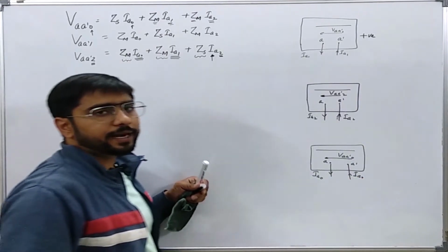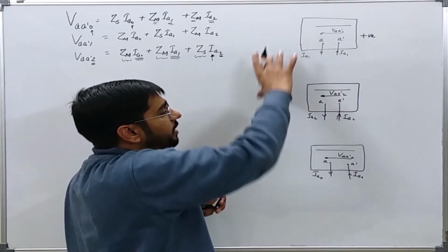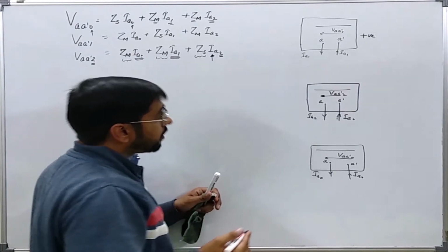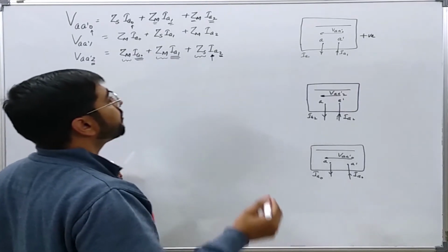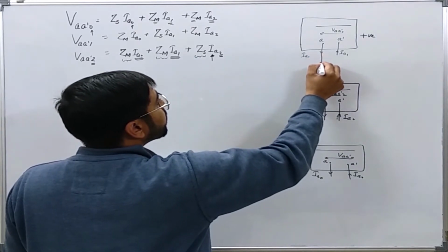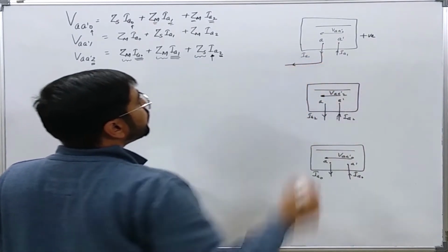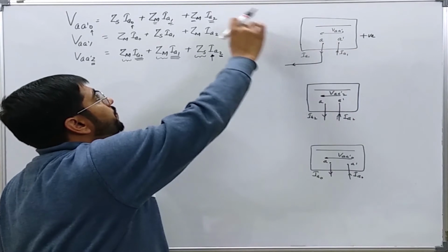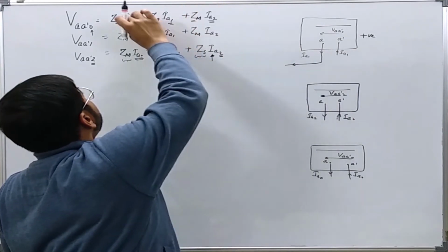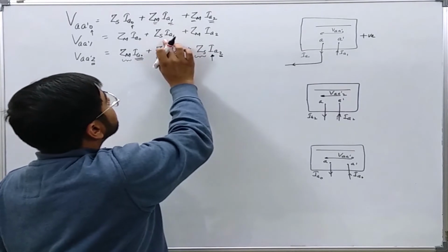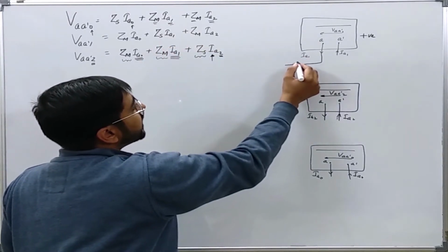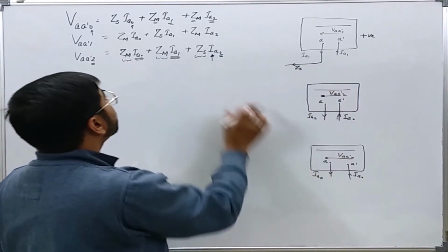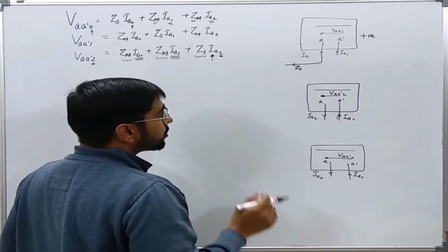Now we need to find whether we can represent these three equations by interconnection of these three sequence networks. It can be represented if, for VA dash 1 only, IA1 for the positive sequence should flow into ZS only. However, IA2 and IA0 should flow into ZM. Okay, so how to do that?